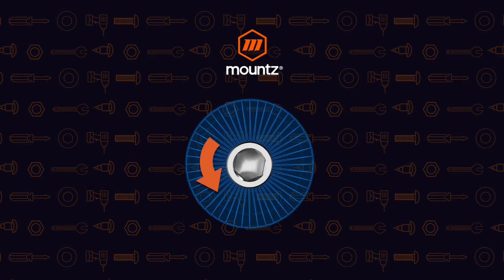The next test is going to be the breakaway test. And this is when we actually just turn the fastener in the loosening direction and see what that value is. Now, this is typically not very accurate because there are some torsional forces that are in the fastener itself. And once you start moving it, that can play a part in the value. And in some cases, you may see a lower torque than what was applied. And so this type of test is not great to use as something that you might want to continuously do.